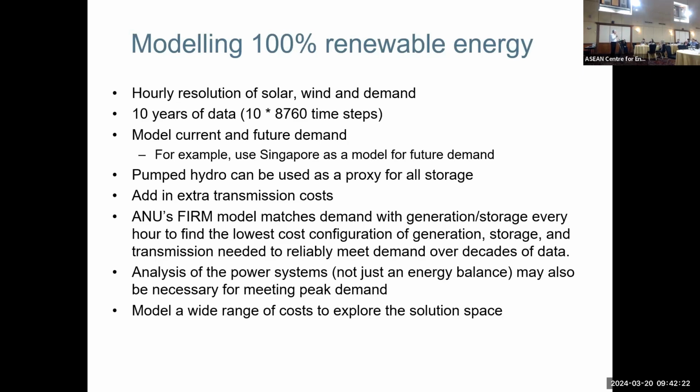Then having done the energy balance, you go back and look in detail at the power balance to make sure that you can indeed meet the future peak demand. And you have to add in, of course, transmission costs. So you end up with generation plus storage plus transmission as the total cost of your energy system in your model.